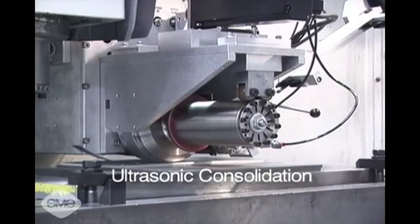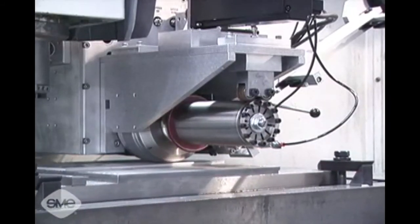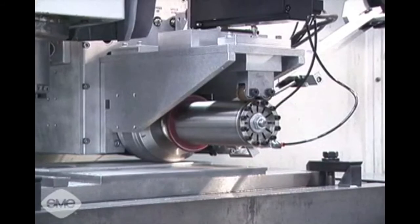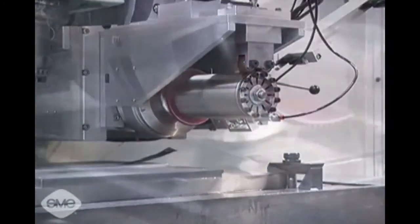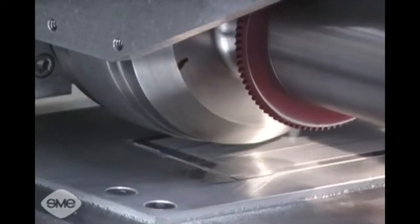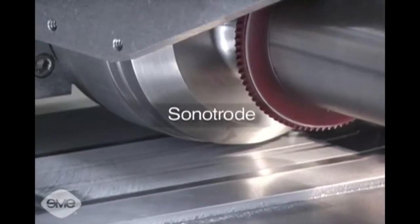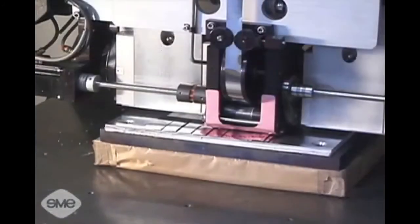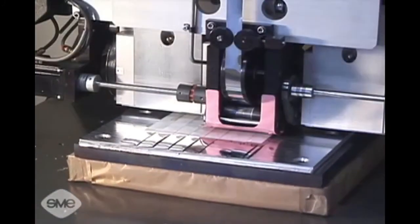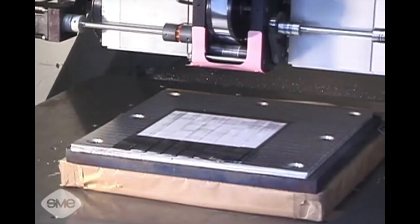Ultrasonic consolidation produces direct metal parts from CAD data by ultrasonically welding layers of coiled aluminum foil strips to a prepared metal substrate. As the foil strips are placed on the substrate, a tool called the sonotrode uses high-frequency vibratory energy and moderate force to disrupt the interface surfaces, inducing interatomic attraction and metallurgical bonding between the foil and the substrate surfaces.